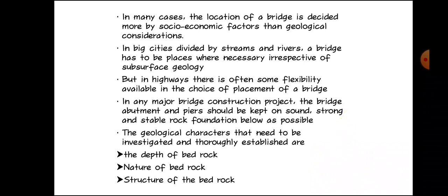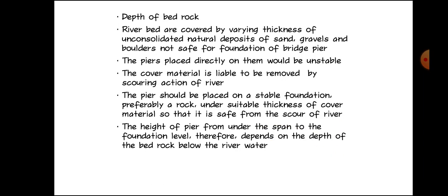The geological characters that need to be investigated and truly established are the depth of bedrock, nature of bedrock, and structure of the bedrock. Depth of bedrock. Riverbeds are covered by varying thickness of unconsolidated natural deposits of sand, gravels, and boulders, not safe for foundation of bridge piers. The piers placed directly on them will be unstable.